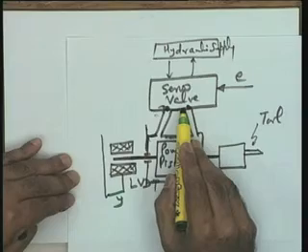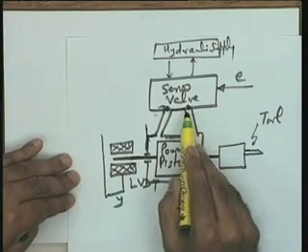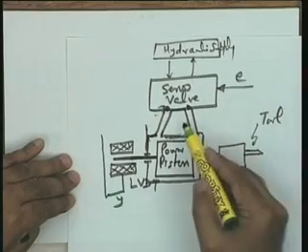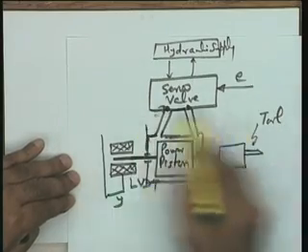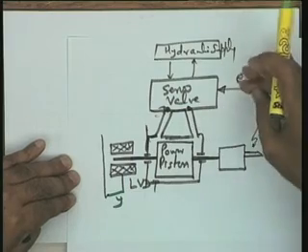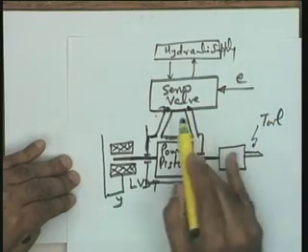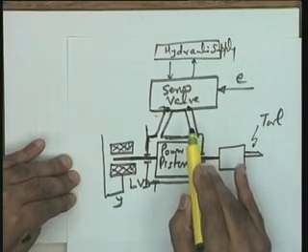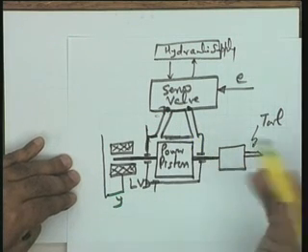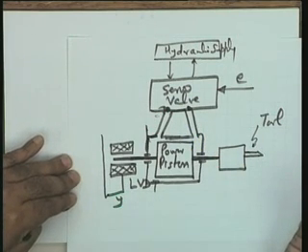EH, electrohydraulic valve, I have already put. This is the electrohydraulic valve. The servo valve I am putting is an electrohydraulic valve which takes an electrical signal as the input and generates spool movement as the output. This I have already used. Electrical signal is the input and the spool movement is the output. Come on please, with the input given to you, you should be able to give an idea. Yes, a differential amplifier will do the job.